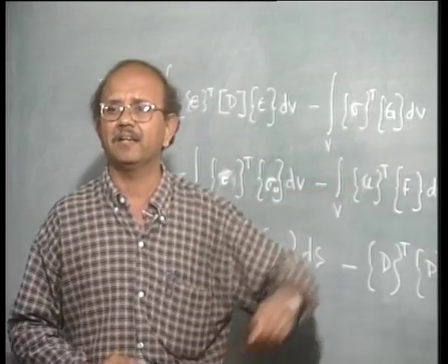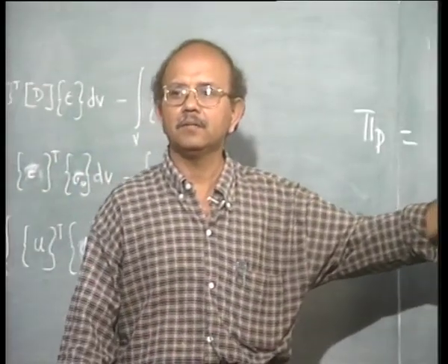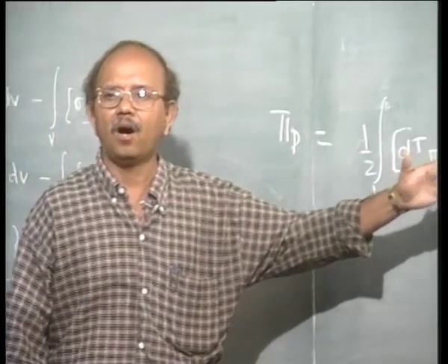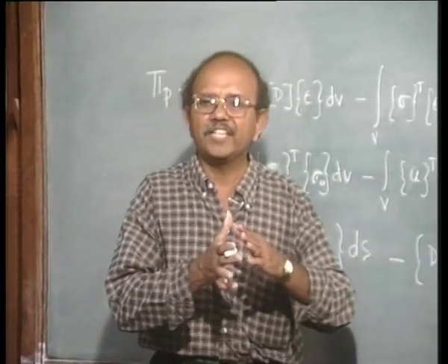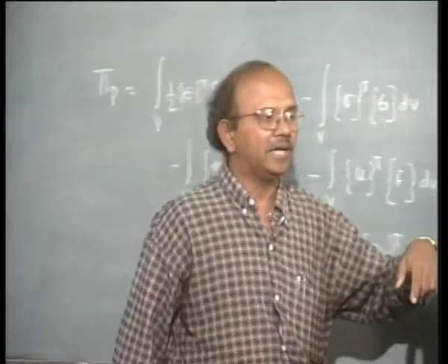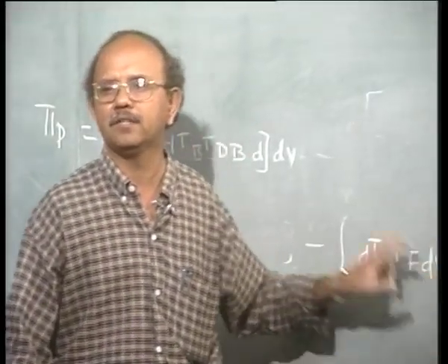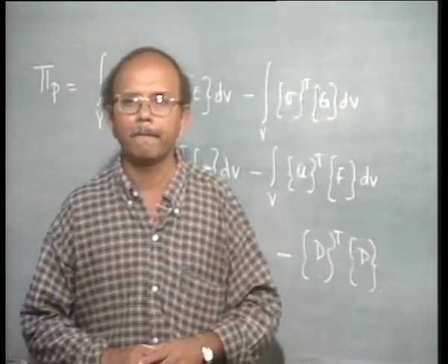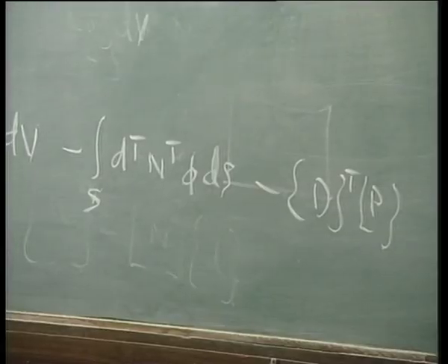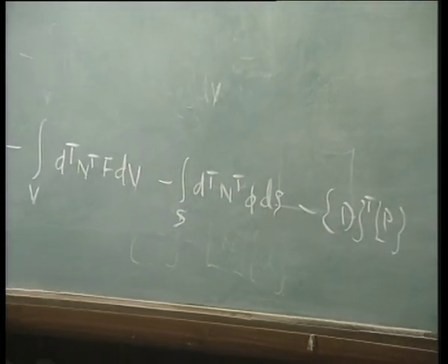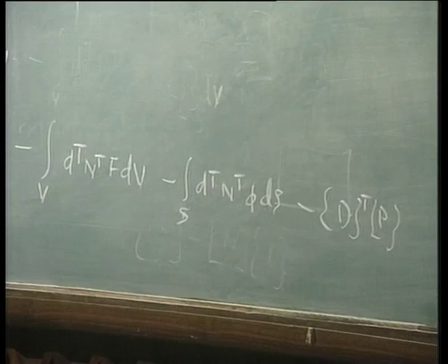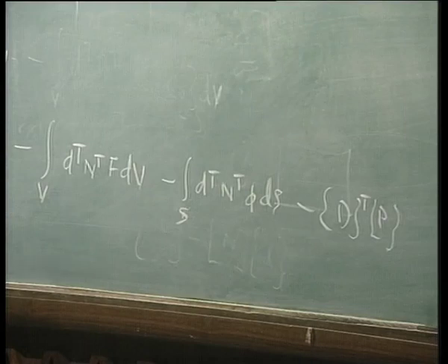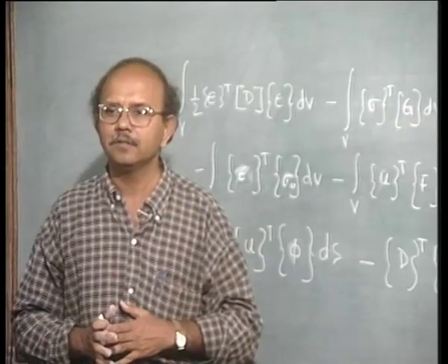So, now I am going to do one more thing. The small d's here are for the element degree of freedom. I am very careful in writing the last term, they do not go with this. So there is always trouble in understanding that. So what I am going to do is to expand that small d to the whole of the matrix. If I have an element which runs from nodes 1 and 2, I will write as if it is 1, 2 and other things being 0, up to say 20 elements, if the problem has 20 elements.